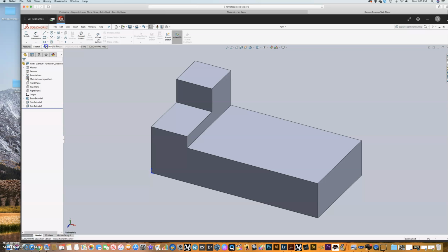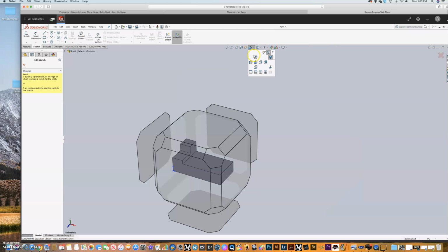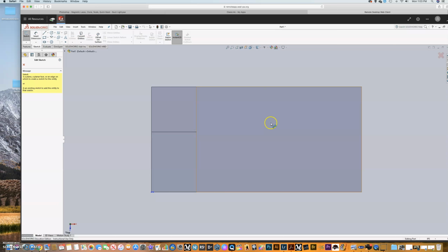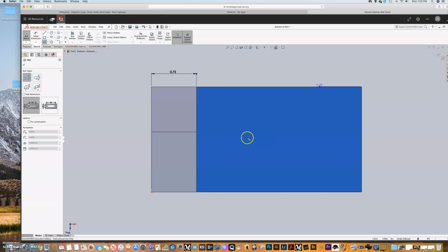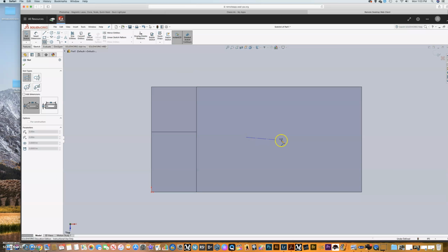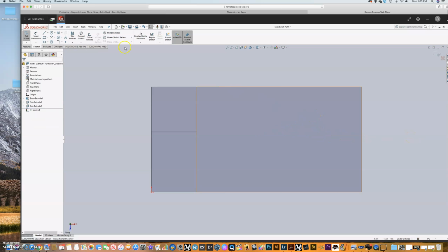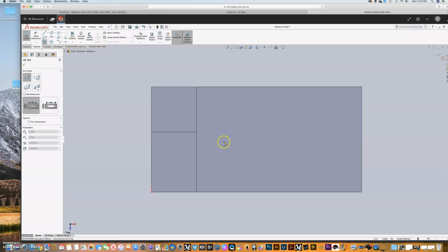The straight is perfect. So what I recommend you guys do, I would go up to here first and I would view it from above, right? The plane that you want to click on is this one right here. And you're just going to click a starting point, and I would drag this starting point out past the edge. So if you messed up, like let's say you did this, just hit escape, not a big deal. Go back to here, click your starting point, drag it to the edge.